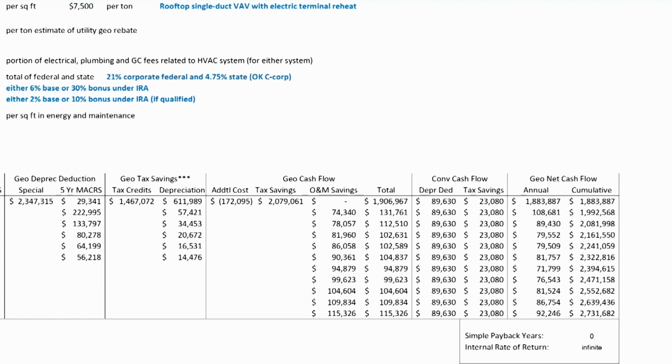Well, I say, your air conditioner is sitting up in that roof trying to dump your heat from the building into a rooftop that in Oklahoma could easily be 115 degrees up there when the air is 105, and you've got these high pressure ducts that require 4 times the fan horsepower to get the energy down to you. You compare that to the highest water temperature we see in the summer, 78 degrees, into a water-cooled unit, which is more efficient to begin with because water is a better heat conductor than air.